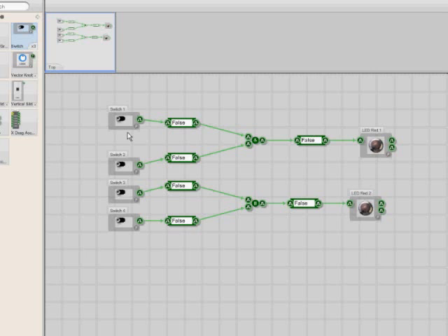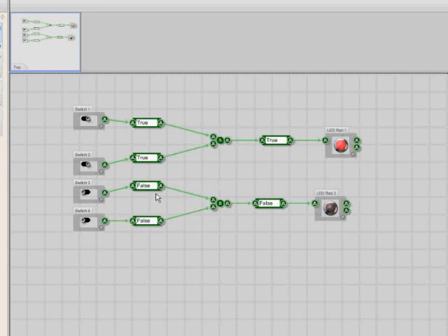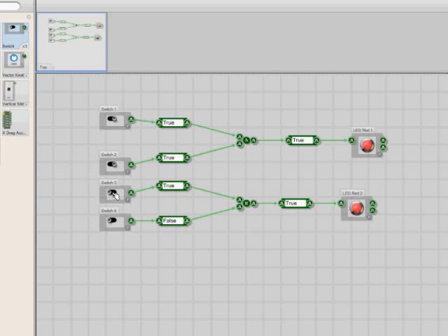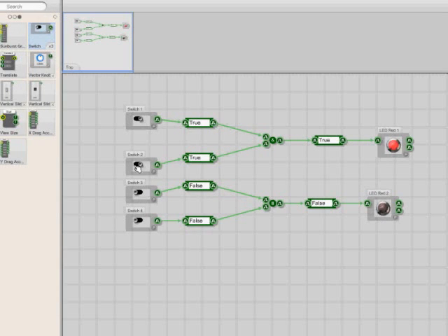Okay, so that's the basis of our Boolean project. Now I can flick these switches, and you can see the effects. 2 ones give us a 1 on the LED output. Excellent. Same on the OR gate. Any 1 gives us a 1. So this helps explain things a lot simpler to students in a graphical way.